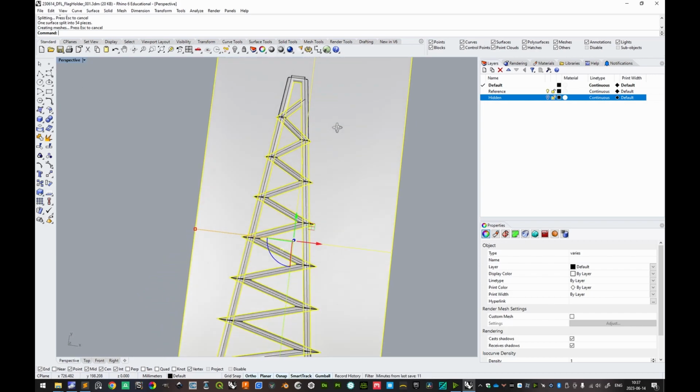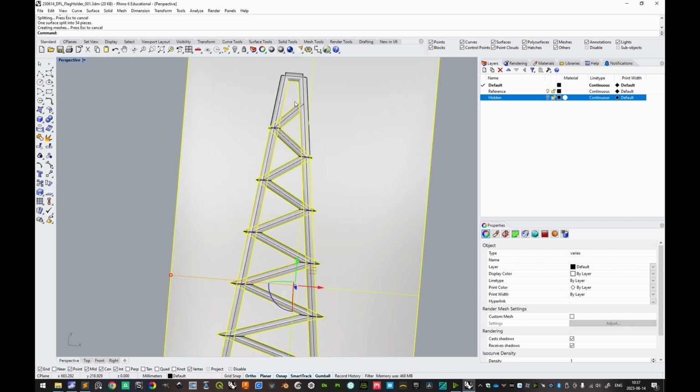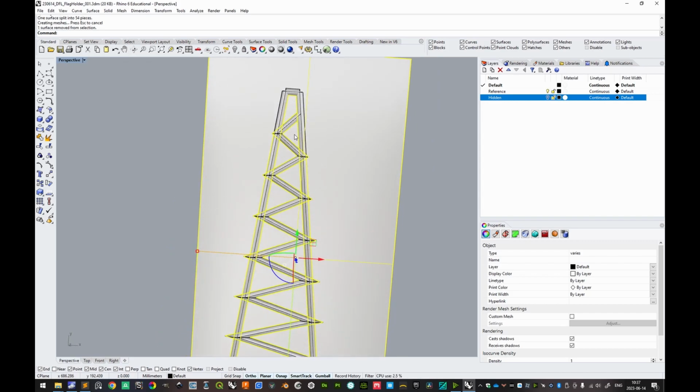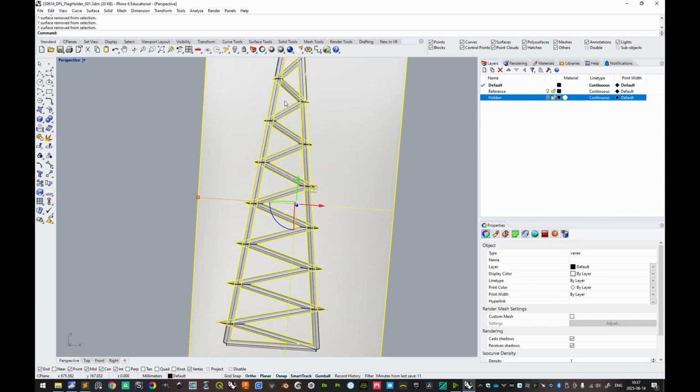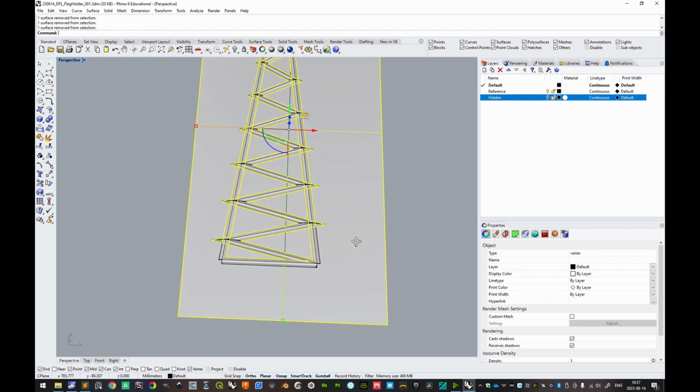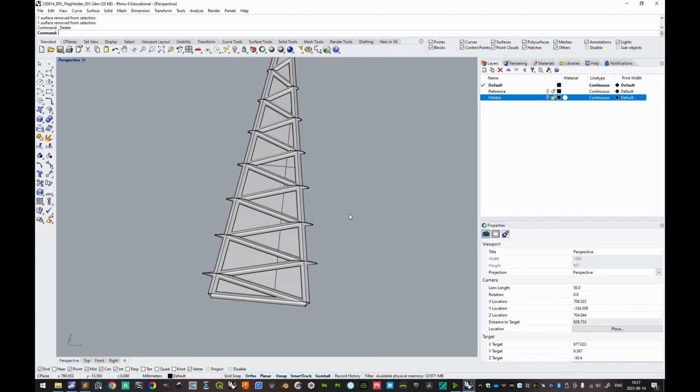Very good. What is easiest here? I think it's easiest if we deselect the surfaces here that we want to contain. So I'll Control click this surface, Control click that surface, Control click that, and continue like this. Since the border edges are highlighted and there are co-aligned edges, you don't see it, but you will see it here. So one surface removed, one surface removed, one surface removed. And here there was an isocurve, so you saw it like this. Just continue with the deselection, like this, and then delete all of the others.